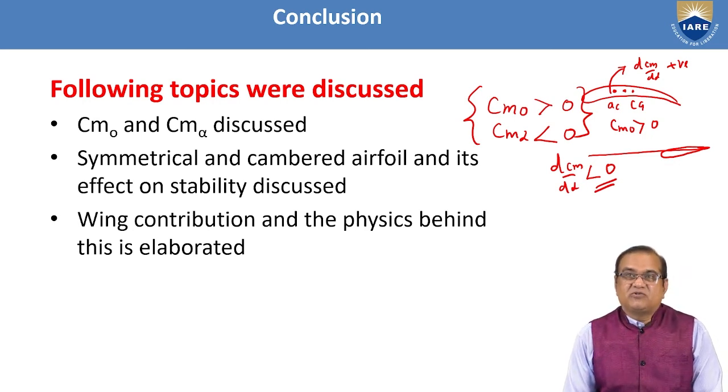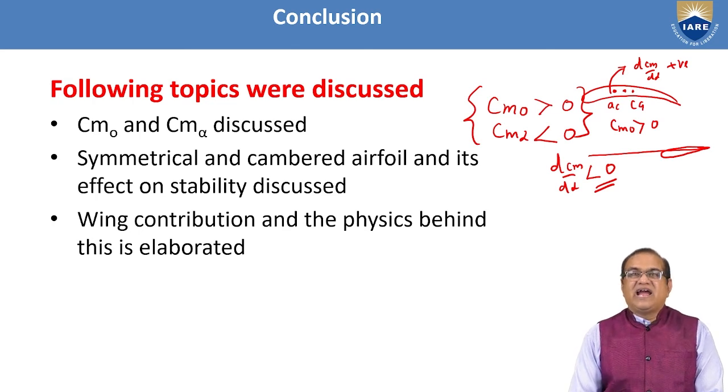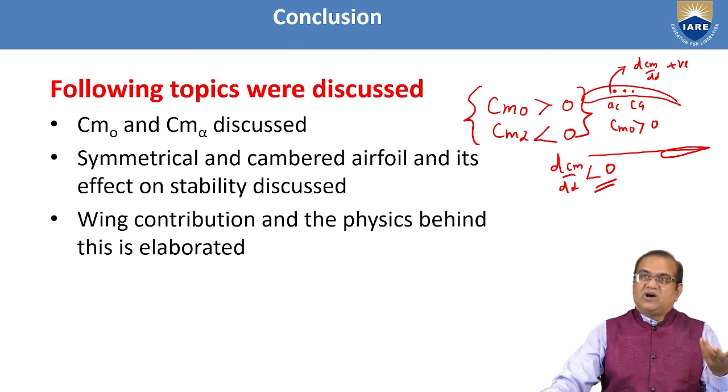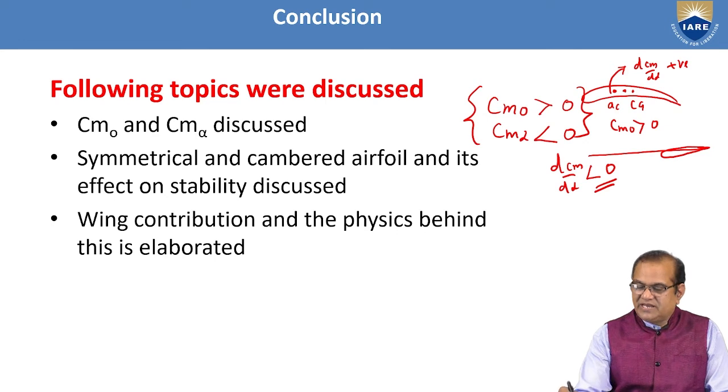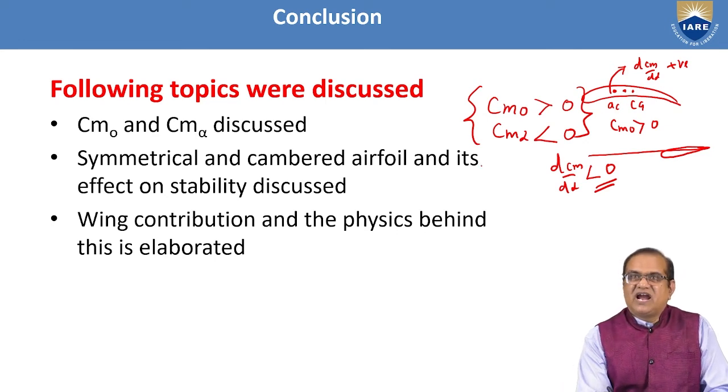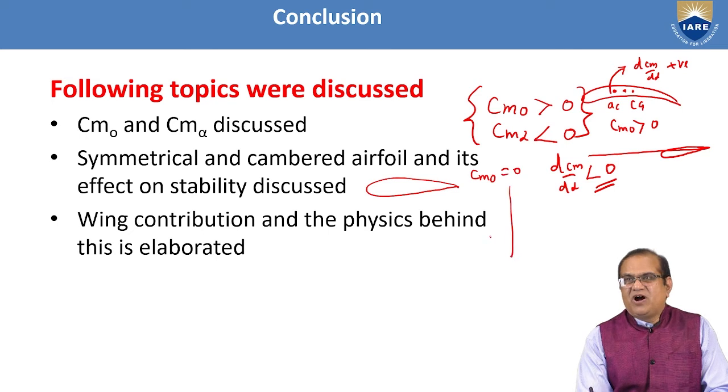Another thing we have discussed is the symmetrical and the cambered airfoil and its effect on the stability. So I have shown you here that for the cambered it is here, and if it is a symmetrical airfoil like this, Cm naught will be 0. So if you make the plot, it will go from here. So you cannot trim in this. You can't trim the aircraft.